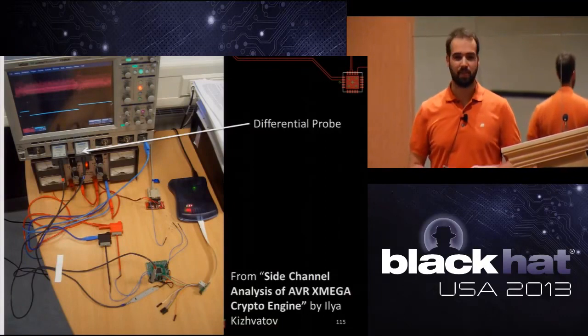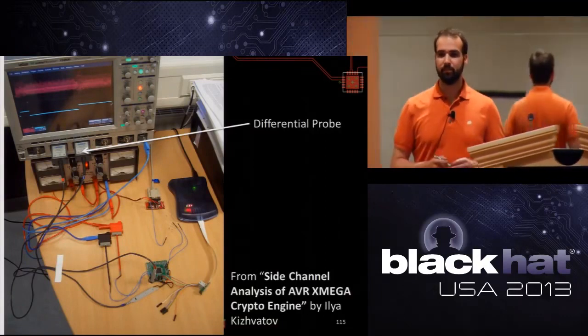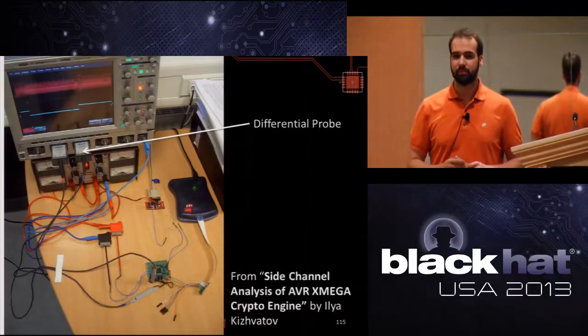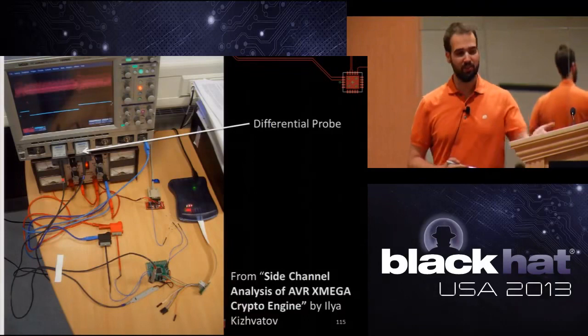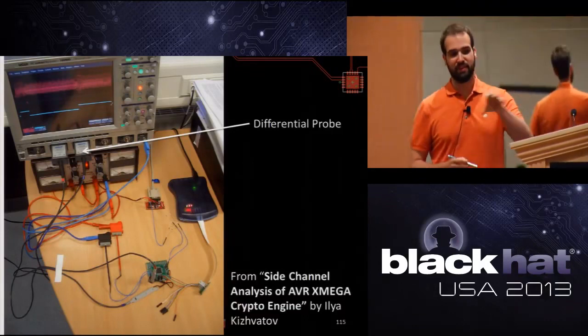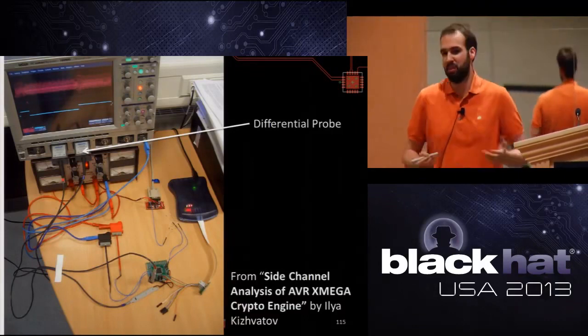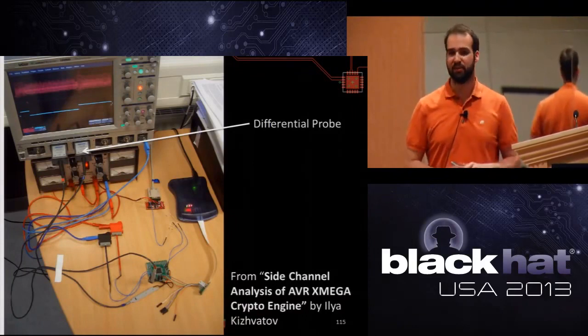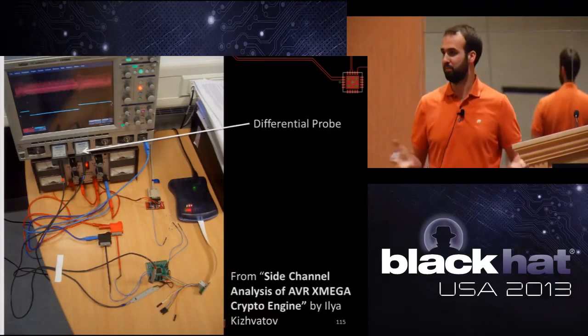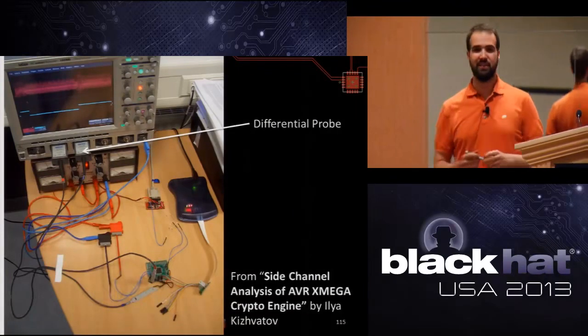Okay, so I'm more curious about devices where it's clearly not AES, just some little cap... Oh yeah, XOR probably. Yeah. I mean, anything where you can figure out this intermediate state, you should be able to. Really, the whole thing is about that you can figure out the Hamming weight of data on the bus. What that gives you depends on what you do with it.